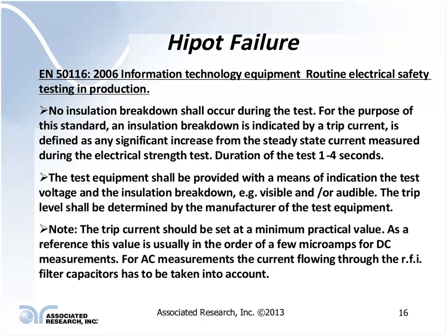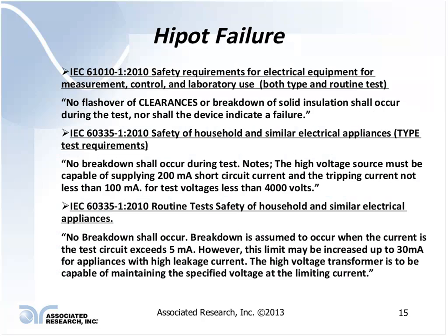One of the safety precautions, I'm going to back up one slide here, is that if you're using a tester with 100 milliamp output on your production line, you have to be very careful with the training and skill levels of your operators. Most of the time, the people in the production environment do not have the training of the individuals that are doing the testing from an engineering environment.